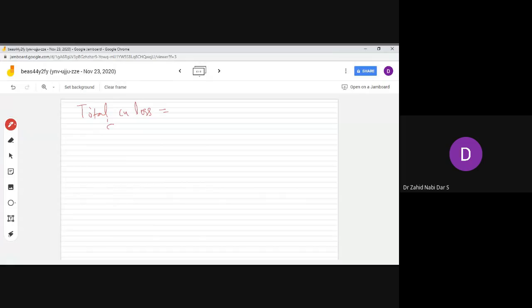In the bar you have SR, the total number of rotor slots, because you are not taking only one slot. In one slot the loss would be IB square into R. So instead of R we'll write rho, rho LB by AB.